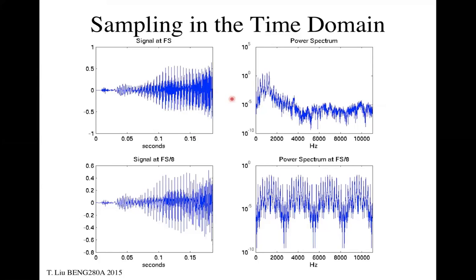So when we look at those amplitudes, that's what the Fourier transform gives us. We plot that normally as either an amplitude spectrum or a power spectrum. The power spectrum is just the amplitude of those coefficients squared.